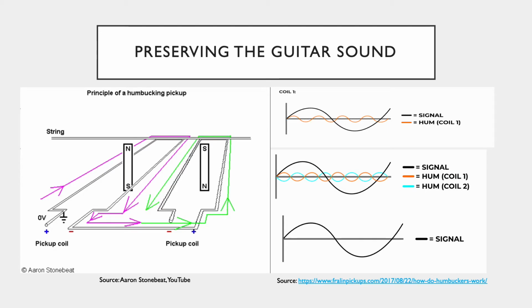So to look at it graphically, this is kind of all three graphs. The hums are going to get met with their counterpart that is going to cancel them out because of the opposite wiring. But you see that our signals are not going to get canceled because, again, we're going to switch the polarity of the magnet. And this diagram here, this third one over here, is a little bit inaccurate because the amplitudes actually are not going to stay the same for the signal here.